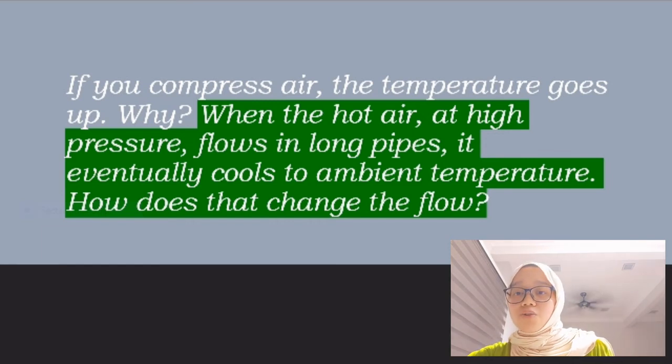Plus, if the flow is at constant pressure and cools, there will be an increase in density and a decrease in volume, slowing it down for the same mass flow rate, m equals rho A V, and flow area.